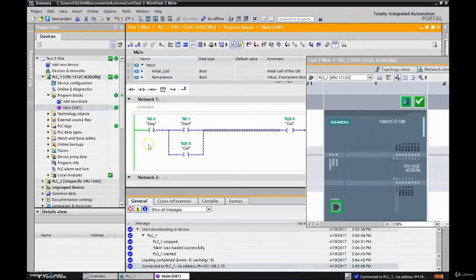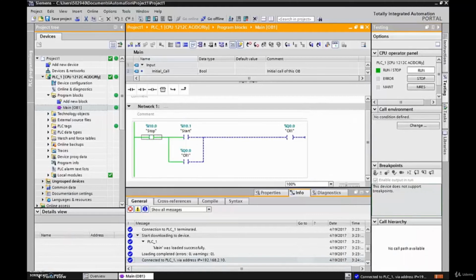Now let's download this to the PLC. So we're going here to download to device. Left clicking on that guy. After downloading to device. Sounds like a plan. So we're going to hit finish. There we go. And similar to the Allen Bradley, this guy doesn't go live right away. So in order to view exactly what's going on with the PLC, because we don't see any green lines anywhere saying that we're actually talking to it, let's come over here and we're going to find monitors. So monitoring on and off. We're going to left click on that guy.